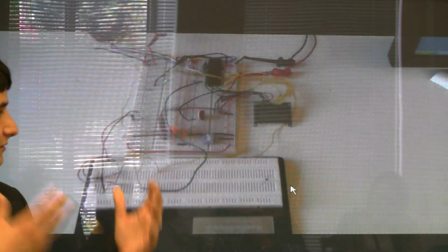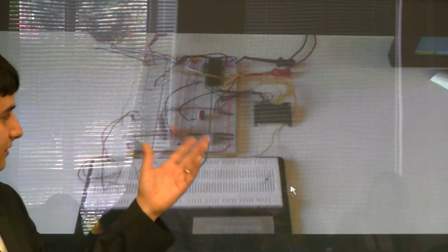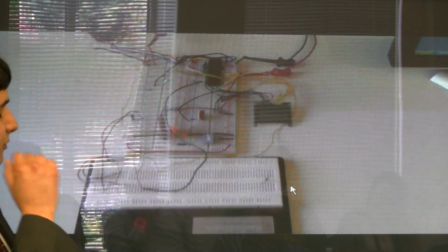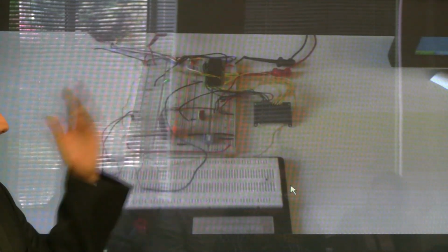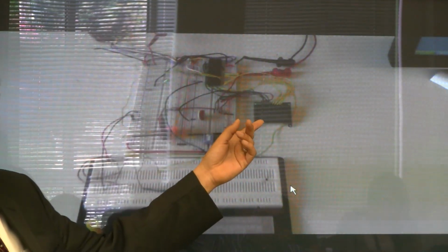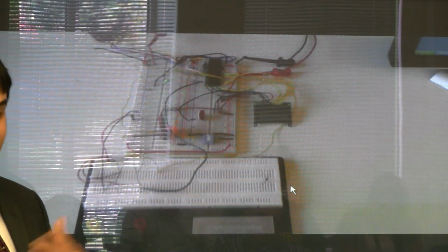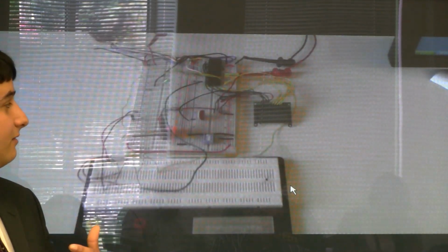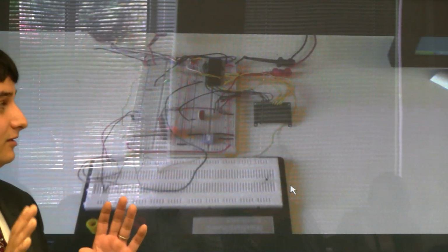When we receive the data from the sensor, we take that into the process and manipulate it, and then we display it. So it's going to zoom in, and you're going to see it update. Then approximately 4 seconds later, I'm going to kill the power. We're going to come back online, and you're going to see the same cutoff values we had stored from earlier. And 4 seconds later, it should update again, showing that we wrote the EEPROM. The purpose is that we're in a month-long time delay, so we want to make sure we test killing the power once while it's running.